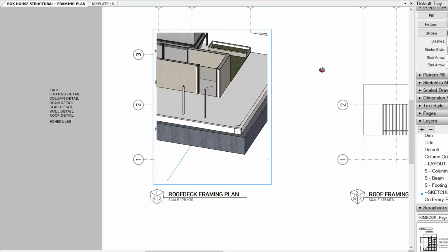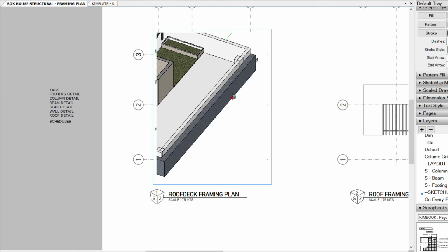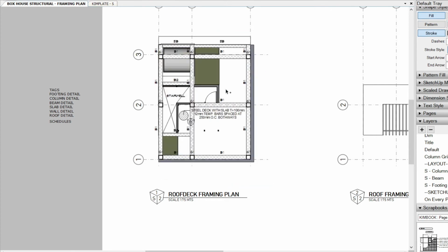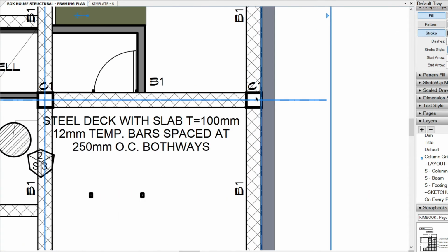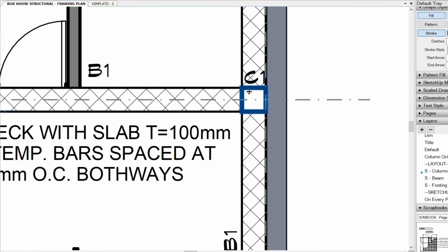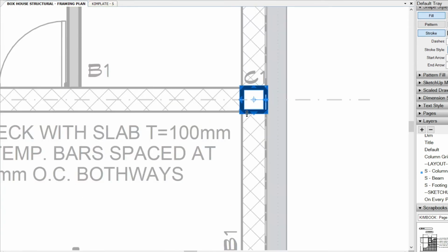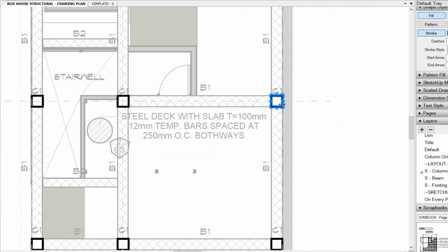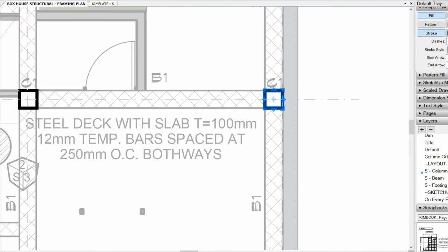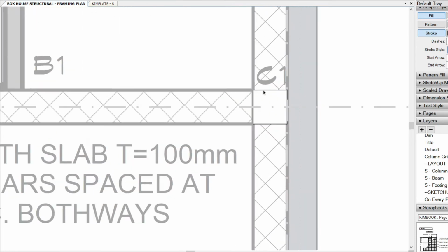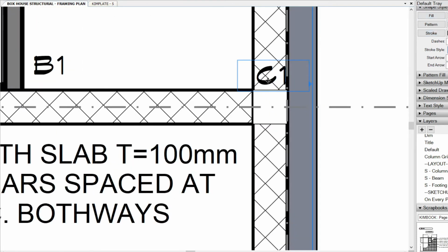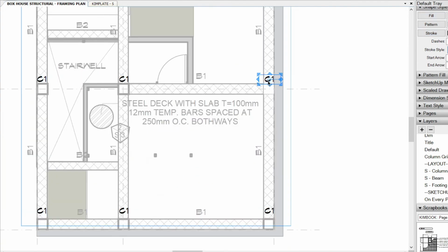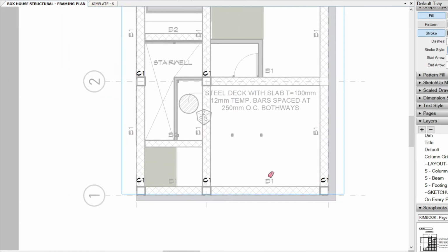According to the design of this box house, then that's all reinforced hollow block. So I have to. If I delete this though, it will look like that. Okay. So I could maybe just make it a very, very thin line to indicate it's a column below. And I'll delete that tag so they won't get confused.